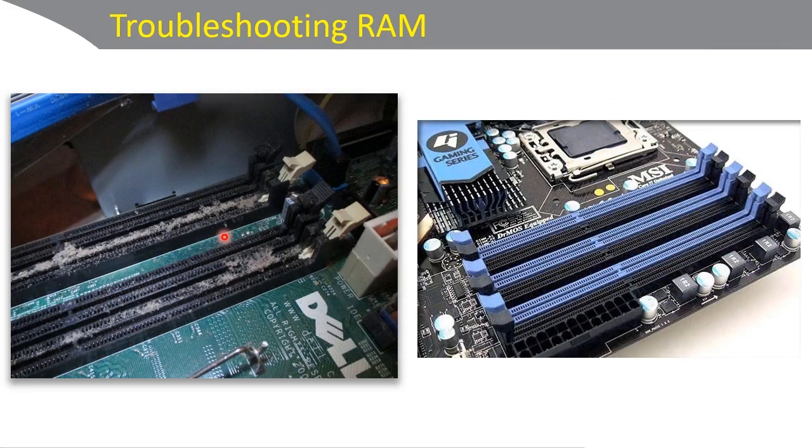So be very careful with this, though. You don't want to touch any of the components. You don't want to generate electrostatic discharge. If you do this outside, you want to make sure the motherboard is inside the case. You don't want to be just walking around with the motherboard, of course.